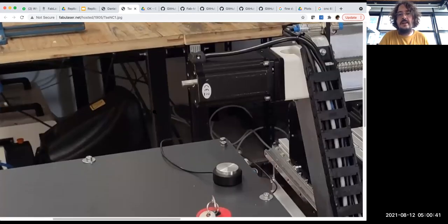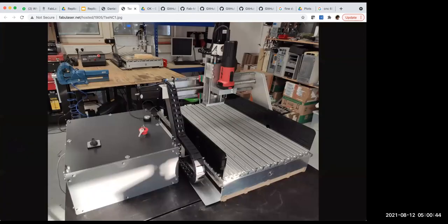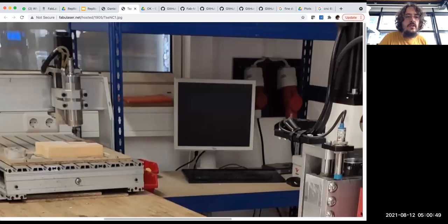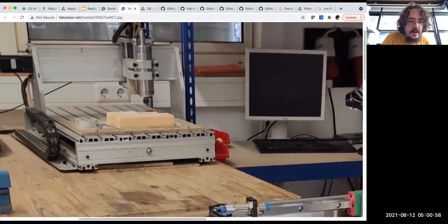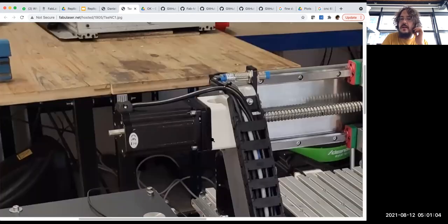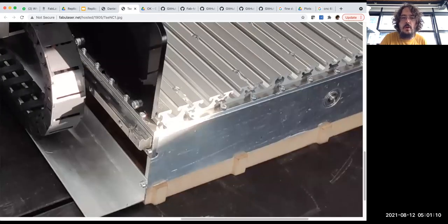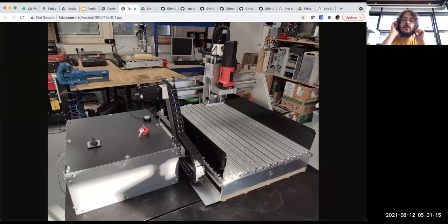But then there is no comparison in stiffness. If you take this spindle by hand here, you're going to twist instantly the x-axis of this machine, and especially you're going to twist this part on the bottom, which is very thin, where these rails are attached. In our machine, really, it's hard to twist something. So it's super solid. Look, it's all bolted here, and here the linear guide is here, and these are like 20 millimeter aluminum profile. Then you will ask me, do you need all these profiles? So this thickness, maybe not. Maybe you need a little bit thinner. So for the next iteration.